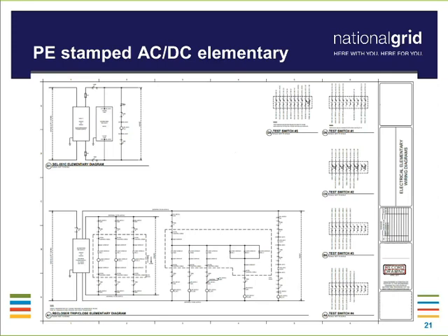And again, that would also have to be a PE stamped drawing. So this one shows basically a ladder logic diagram where it shows all the inputs and outputs of the functionality of a specific relay. And that gives us a clear picture of how this relay is going to operate, what functions are being driven. We can trace the functions to different trip parameters or conditions or sequence of events that we would require.